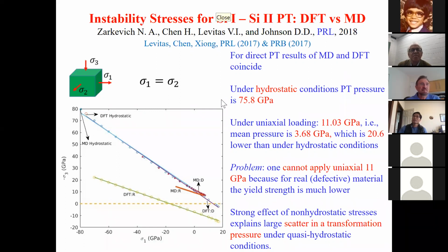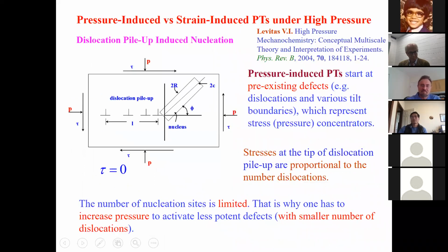Material under high pressure or severe shear deformation, at the atomic length scale, can we use the dislocation pile-up model? Under that deformation, maybe dislocation pile-up makes the material amorphize. At the atomic length scale, the dislocations are really individual dislocations. Can you make a comment?